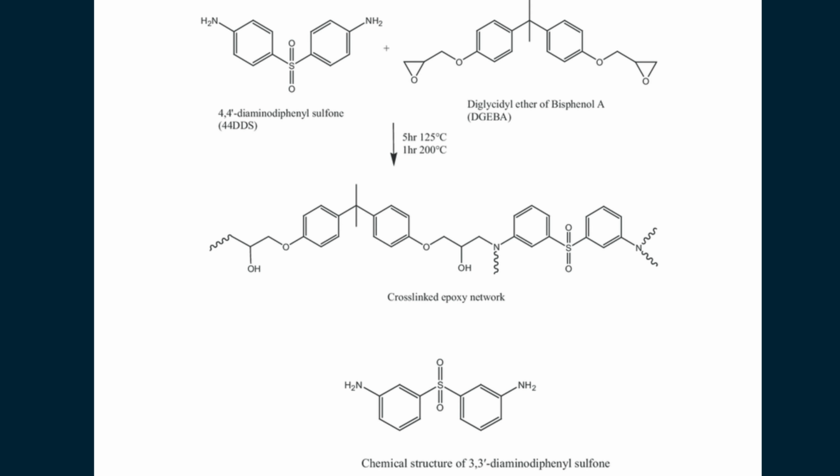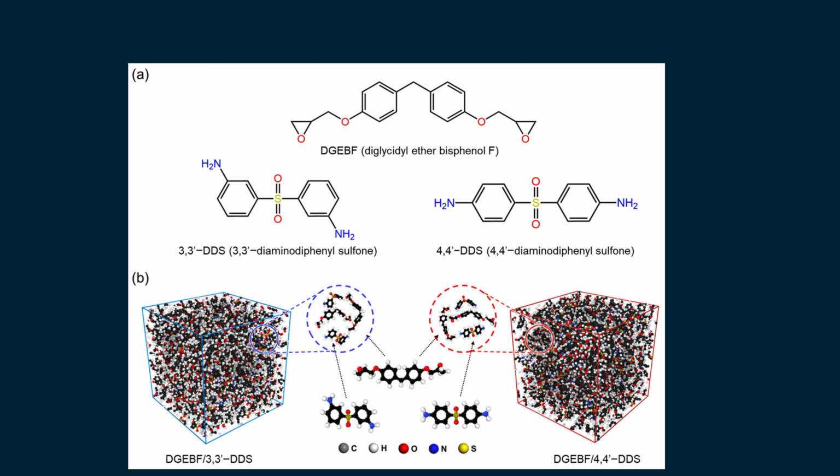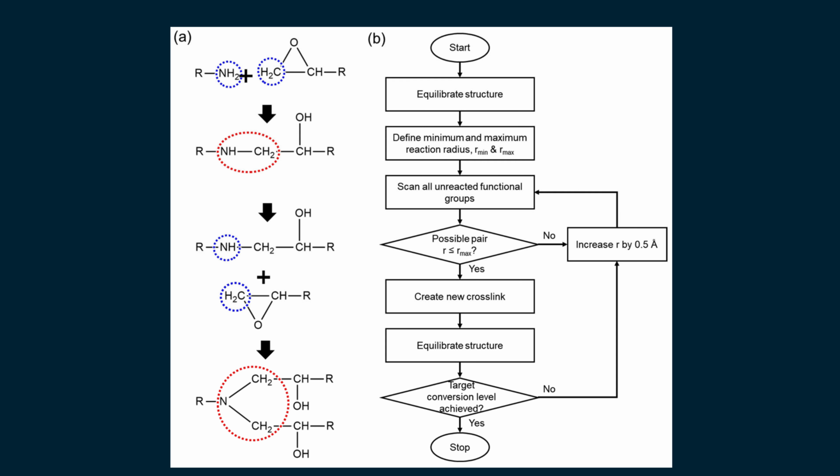Because it is relatively unreactive at lower temperatures, it can be mixed with epoxy resins at elevated temperatures without premature curing. This curing agent produces epoxy networks capable of maintaining mechanical strength at very high temperatures. For example, formulations based on tetrafunctional epoxy resins cured with DDS can retain bond strengths exceeding 1000 psi at 260 degrees Celsius after appropriate curing cycles.